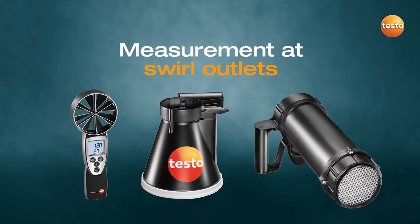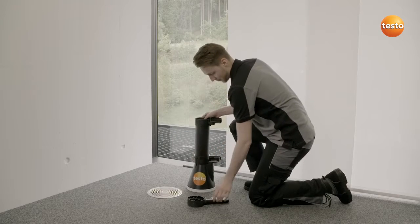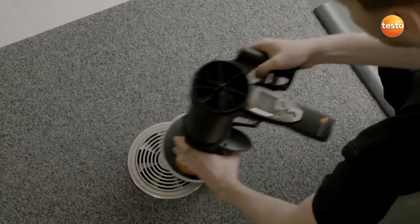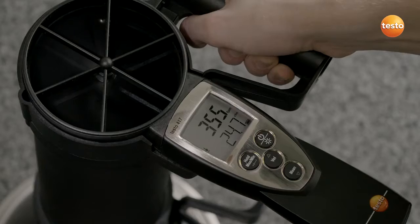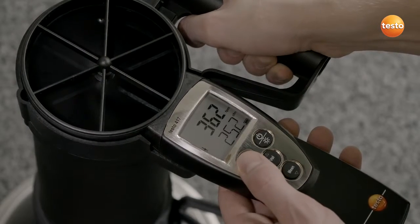This is how you measure properly at the swirl outlets. Measuring the volume flow accurately at swirl outlets is often a challenging task because the supply air is fed into the room in a circular motion, making an accurate measurement difficult. Why is that? Vanes can only record the flow accurately if the airflow hits the vane vertically. The flow straightener ensures that the airflow passes over the vanes in a single direction.